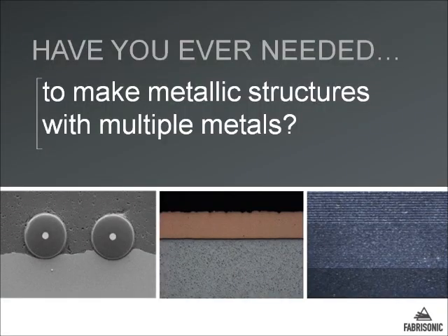The key differentiator between ultrasonic additive manufacturing and other metal additive manufacturing techniques is that it's a solid-state welding process. Solid state means the bond is created without melting the material. In fact, generally, our process happens at only 200 or 300 degrees F. Those are the highest temperatures we see when welding aluminum. Solid state is very important in that it gives you the ability to do many things.